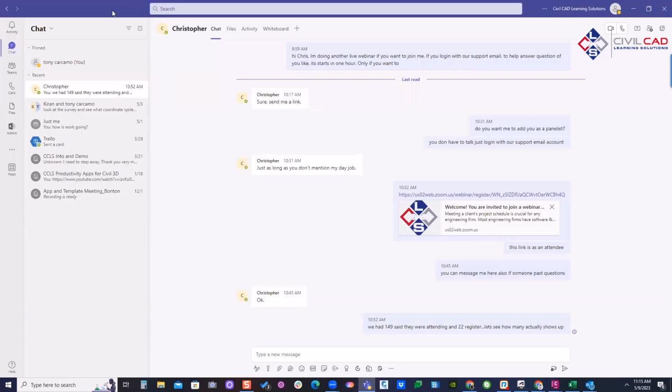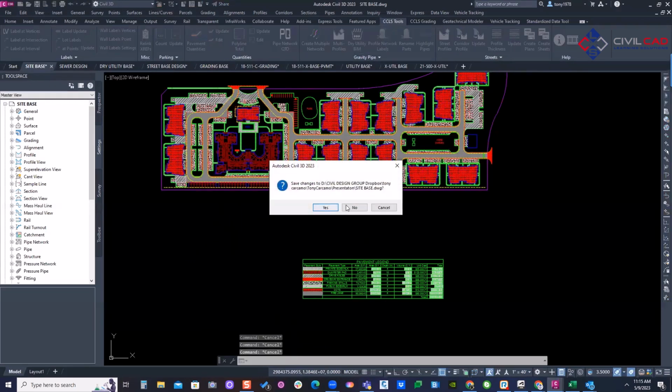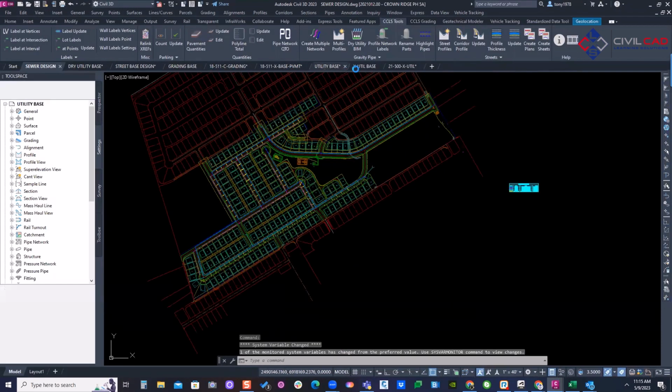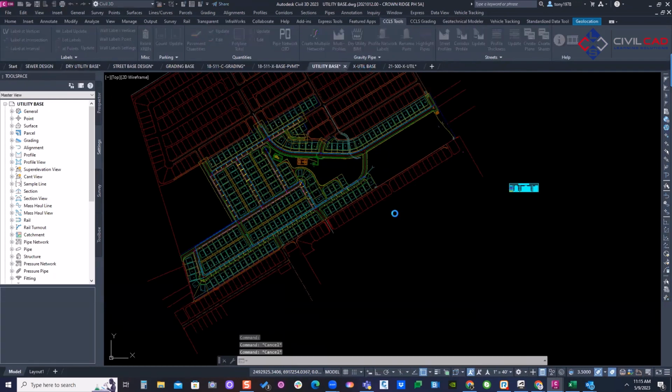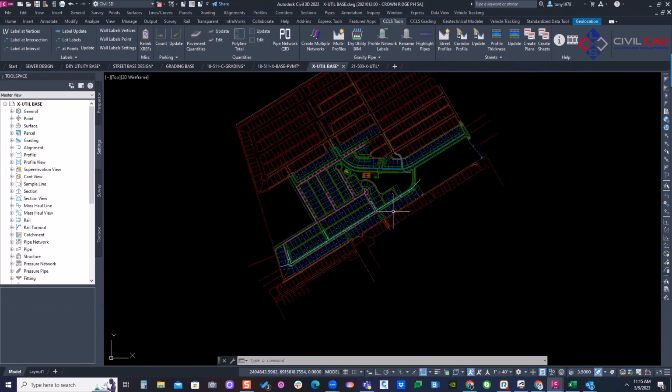All right, let me move on to the next one. And we're going to talk about street profiles. All right, so I'm going to close this and close the other one. And that polyline total can also be used for maybe striping. Maybe you got some line work and curbing. You're doing a transportation project and you want to get total length of sidewalks and curbs and barriers and fencing and retaining walls. That's another option you could do, is run that out based on layers and get quantities on those items on a public transportation project.